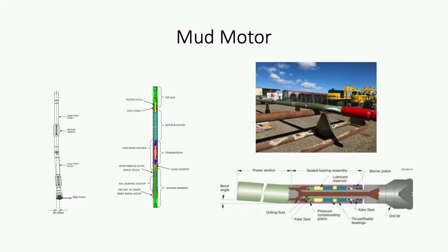So when it's spinning around and just rotating, we're drilling the well completely, just rotating. But when we stop and we keep pumping on it, it'll turn the bit, but the motor won't turn. So when that happens, we utilize that angle and push down on it, and it'll start to turn like that. So that's what we call sliding. So we'll stop and make our calculations, and they'll say, okay, now we need to go 270 degrees, and we need to put in 30 feet to keep on track to our direction that we want to go. And how sharp a bend can you make?